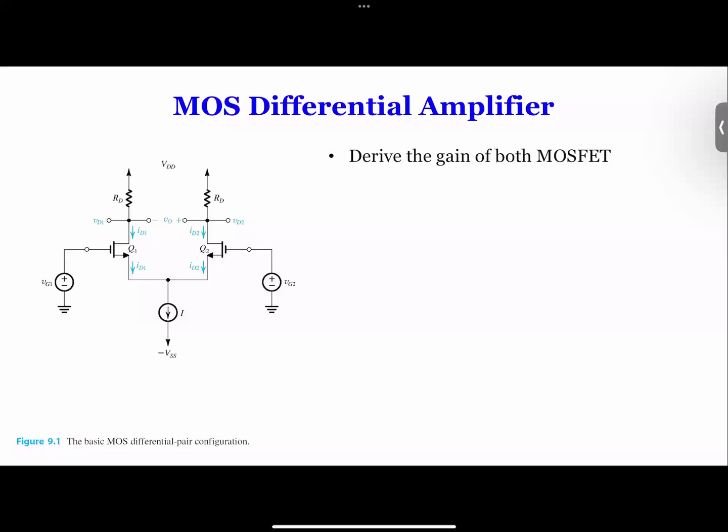So this is a differential amplifier. A differential amplifier would, by meaning, have 2 input terminals. So you would have a terminal input over here and an input over here. So you would have 2 terminals that you can take the differential. Now, we use this to illustrate how this works. In real life, you don't have to have 2 separate voltages. You can connect them together to have 1 input. But this is to facilitate the analysis of the circuit.